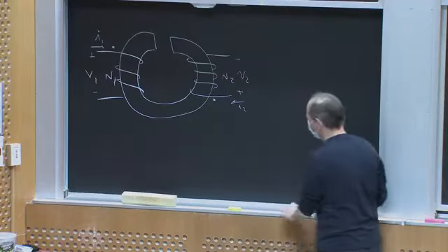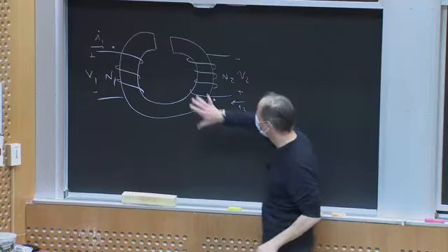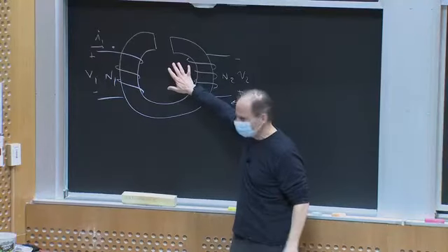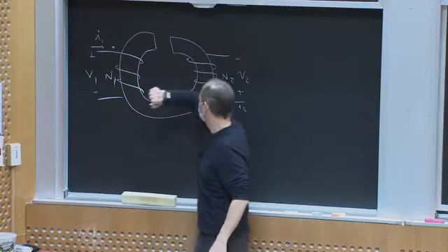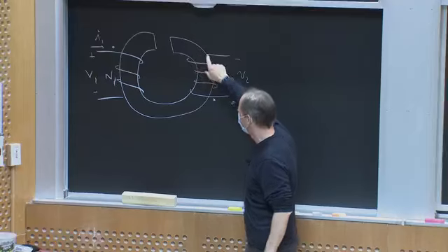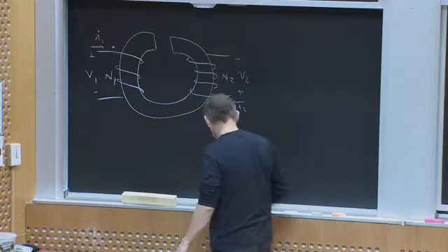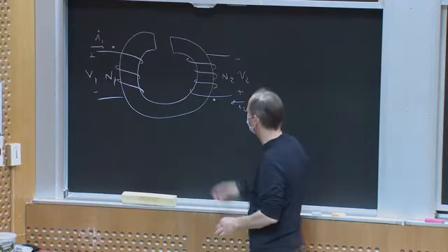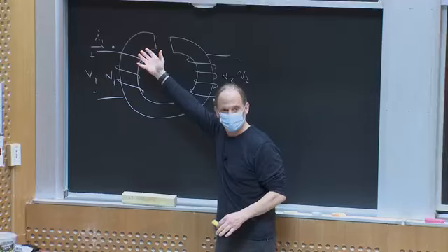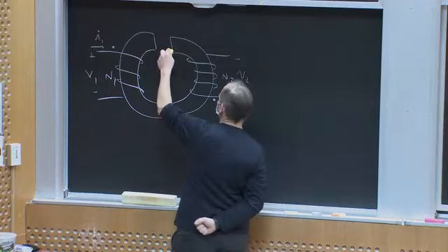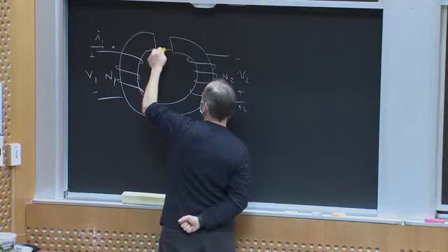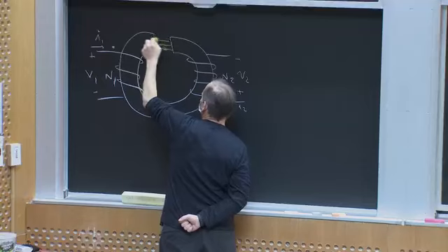And the notion is, where is the energy stored in this? Well, physically, there's some current in winding 1 and some current in winding 2. And between the two of those, they're having induction between the two coils, and there's some energy stored in the field, in the H field, which will mostly appear in the gap, right?